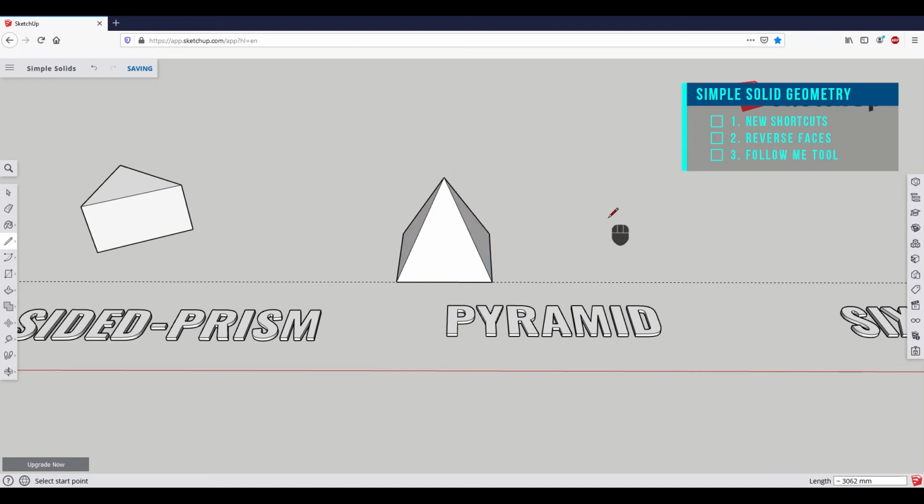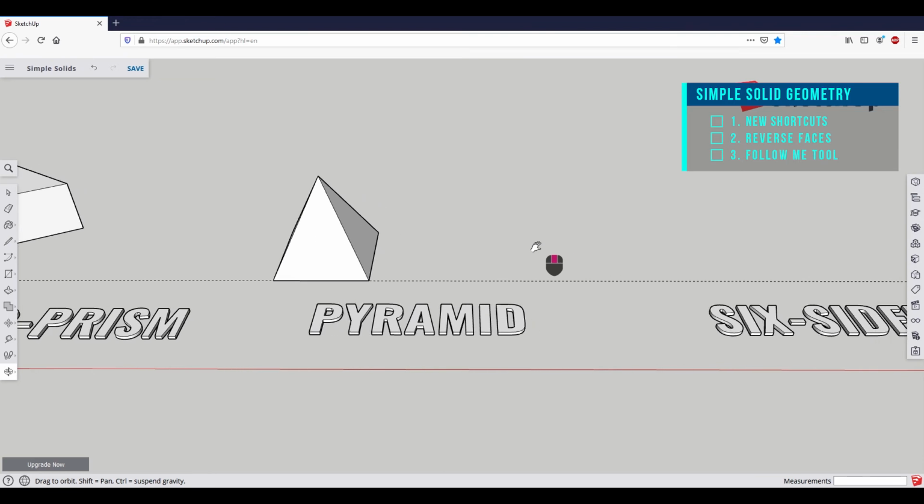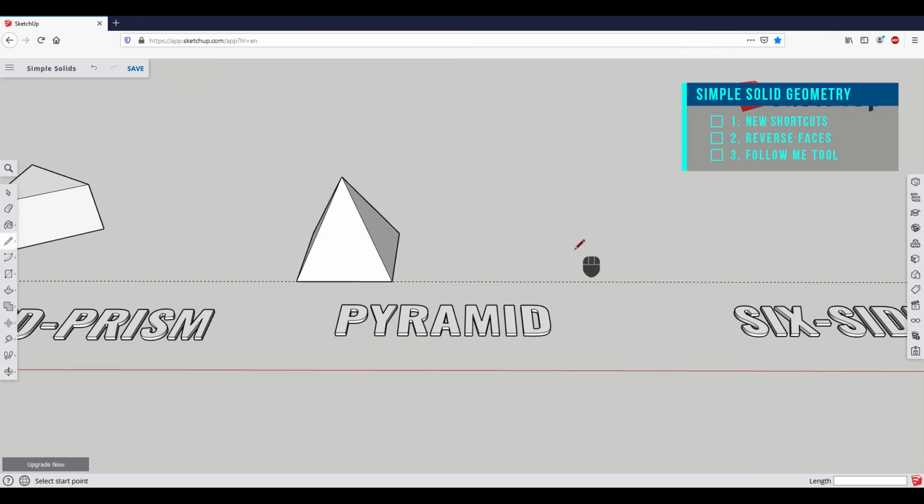Creating the pyramid this way contains a lot of drawing and erasing, so there must be a better solution. Can you remember how we created the roof in Chapter 1, Episode 6? Let's apply this method to create the second pyramid. We start out the same way. Press the R key for the rectangle tool and draw a new basic shape. After left-clicking, we can enter the same dimensions like before.